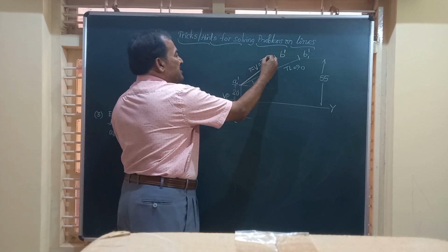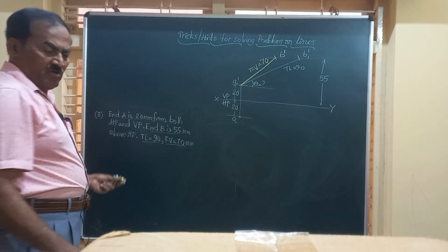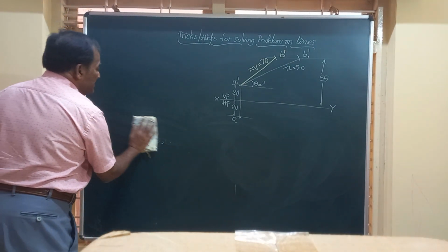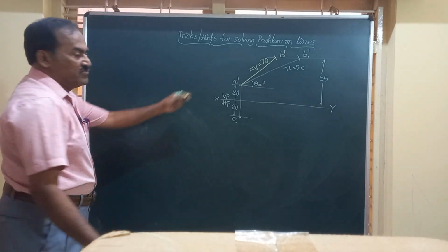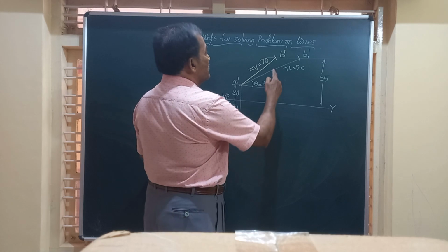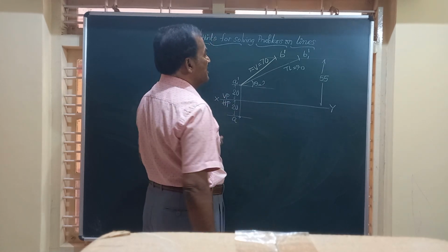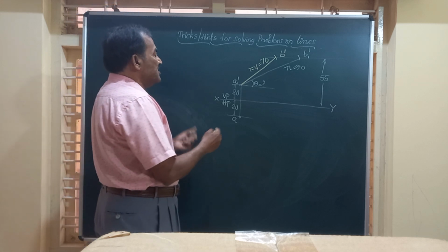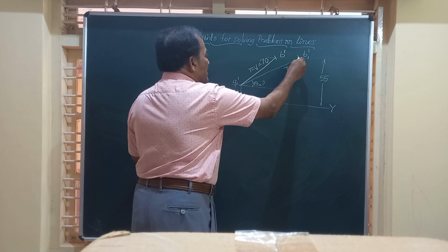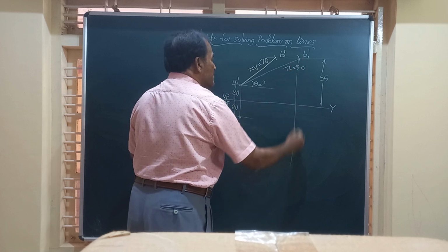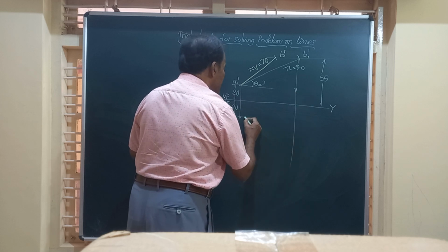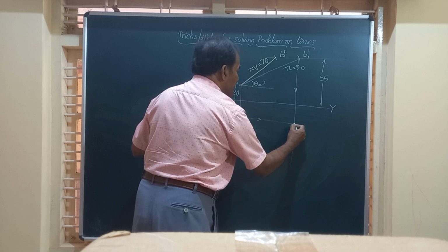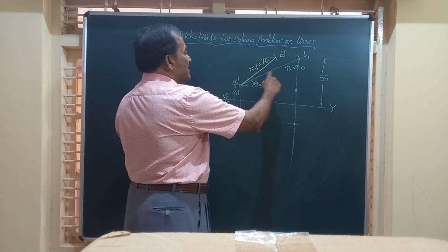Friends, if you look at the question, all the information given in the question is exhausted. Now, with this skeleton, we should be able to obtain 2 points, that is B and B1 here. Friends, how to obtain that? Here you have this true length line. You can draw a vertical line from there, till it touches the locus of A in the top view; it will meet here. Friends, we have made this line like this.